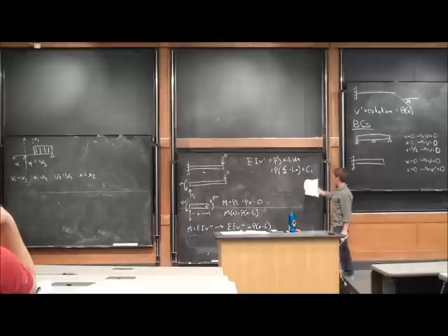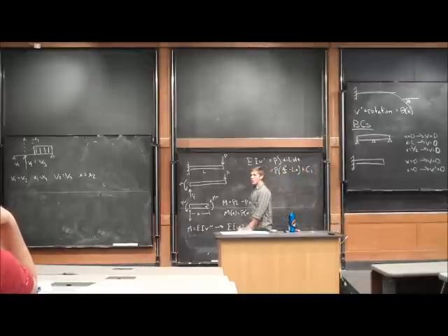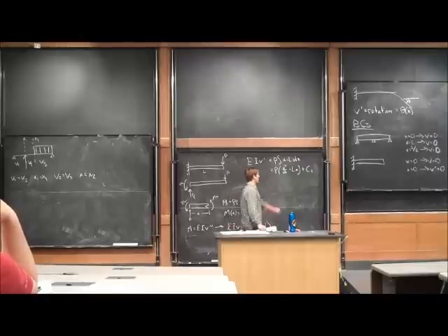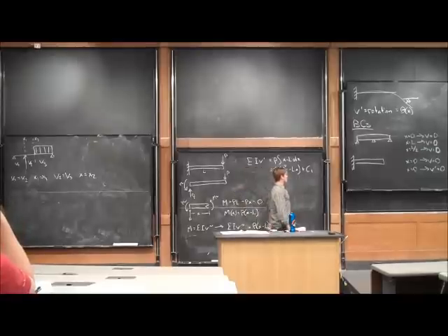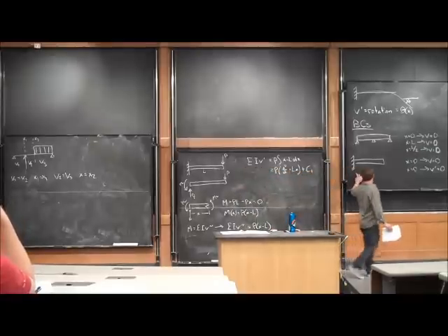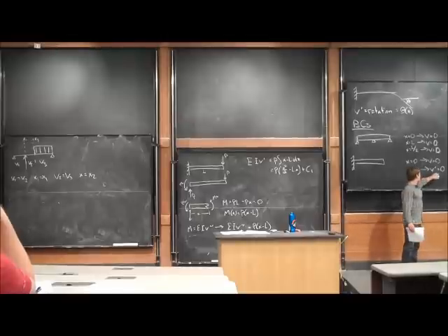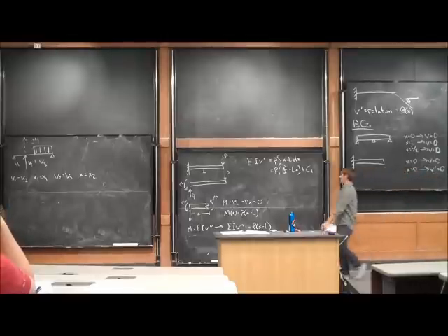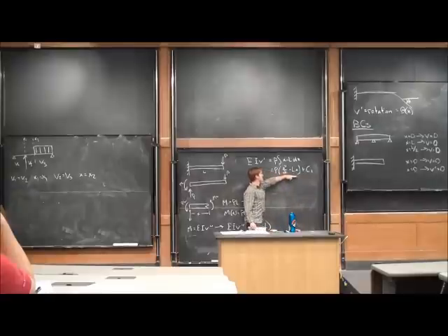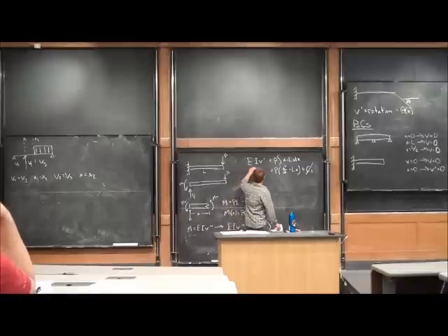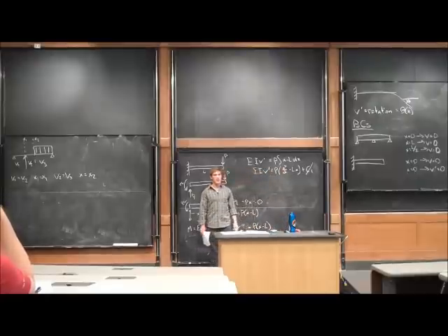So, we go ahead and start applying boundary conditions. If we apply them now, we don't have to worry about it later. If we can get rid of C1 when we integrate again to get our deflection equation, we don't have to worry about it being an arbitrary constant. We know that for cantilever beams, at X equal to 0, the displacement is equal to 0. So at X equal to 0, this term goes to 0, so this term must be equal to 0, so C1 has got to be equal to 0.